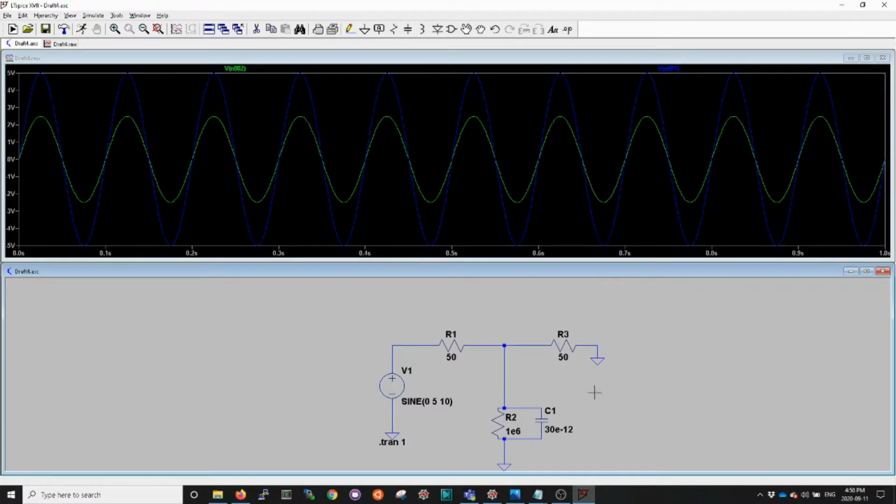At some point in this lab, we were sending AC signals into the scope and seeing when they attenuate. So let's see if we can understand this a bit better by explicitly simulating it. So, by the way, if you want to delete sections of your circuit, just press the delete key and this pair of scissors will show up and then you just snip away. So let's put the scope in a different position. Let's pretend that we're just sending a signal straight into the scope. So let's move it to the other end of the resistor.